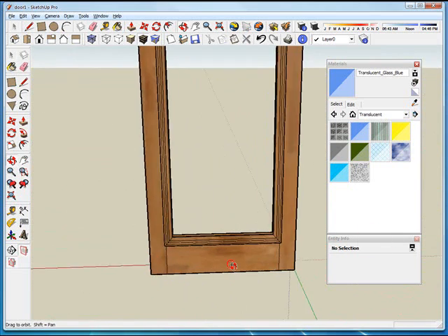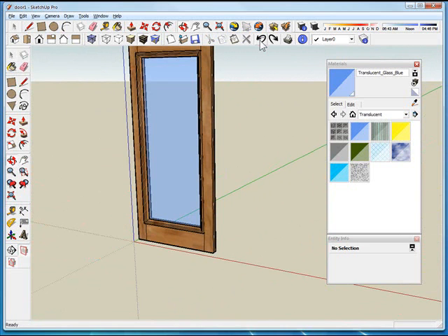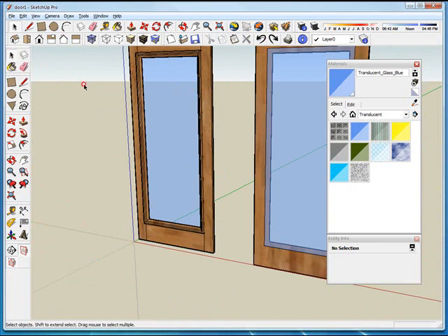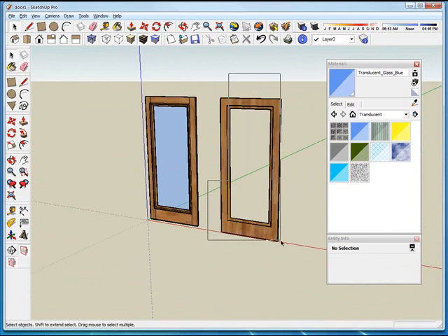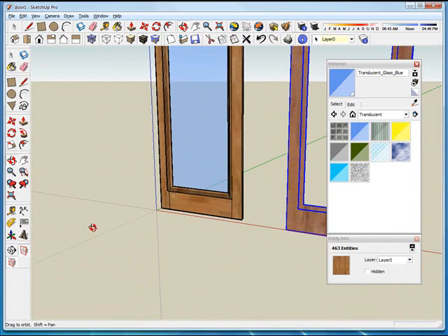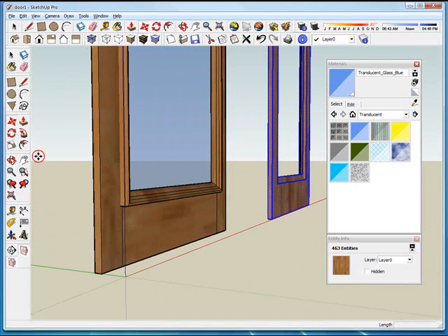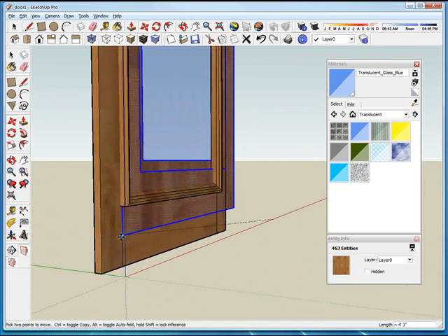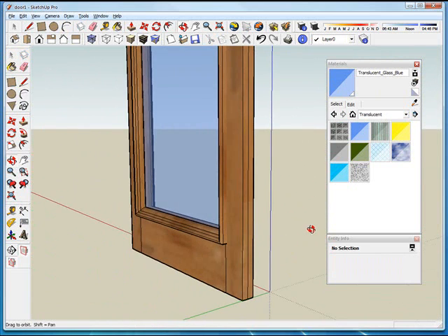It sure did. So what I'm going to do is I'm just going to backstep it, and then I'm going to take out that piece of glass. I'm going to select it all and apply it to the back again. Now the reason why I want to do that is because I've found with too many layers of glass in a ray trace on Chief, the glass doesn't show up very well. So it's always best to be one-sided and to make sure it's all actual glass. Okay, those two lined up pretty good.